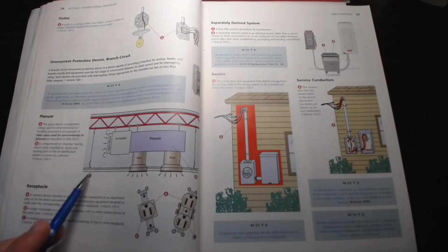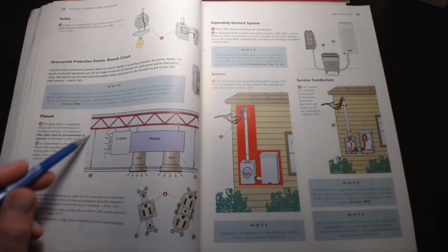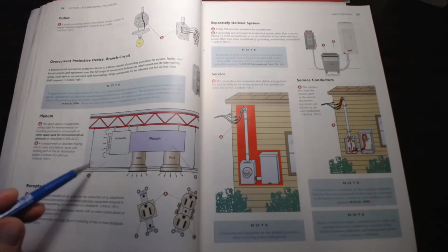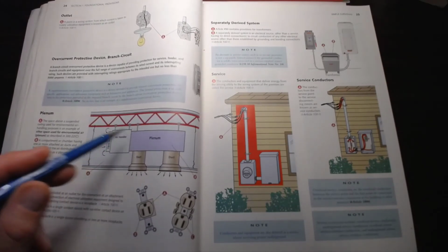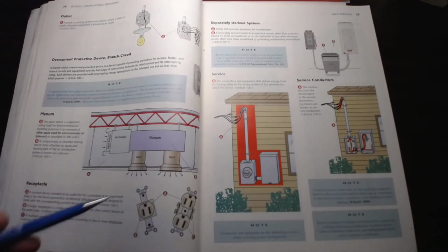That grill would be set into a ceiling tile space, and there will be no duct connected to it up to the air handler. So the air just comes out from below and up into the plenum space and back into the air handler to return into the air conditioning system.